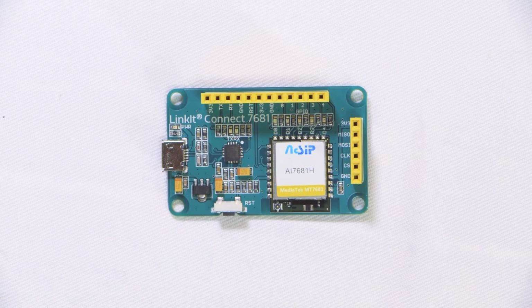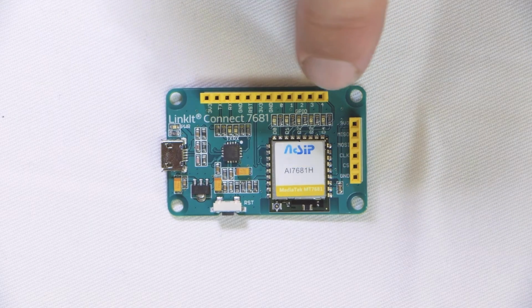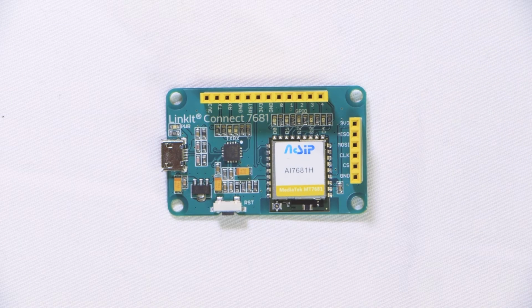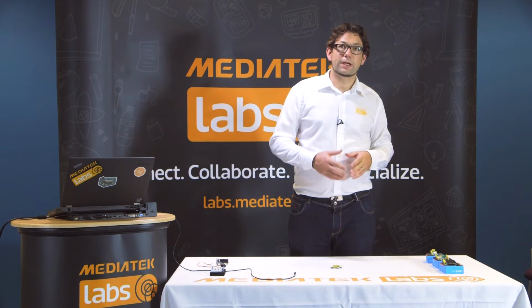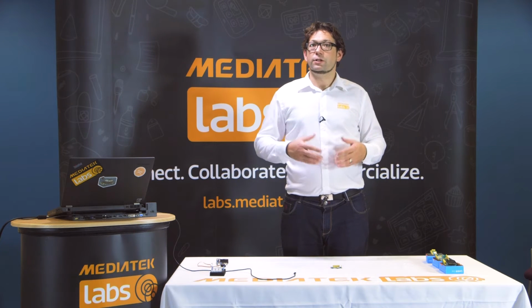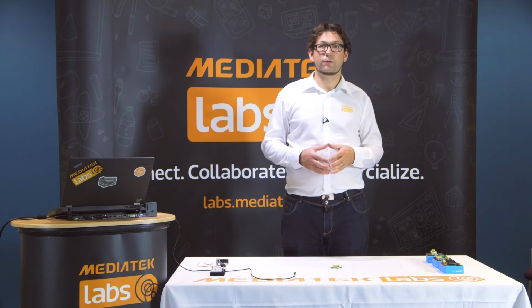It's quite a small one, and it has 5 GPIOs and it's a Wi-Fi SoC. So it has its own operating system running on it, and you can control the GPIOs. You can connect to a web server through TCP/IP. You also could control the UART port. So there's quite a lot of flexibility.